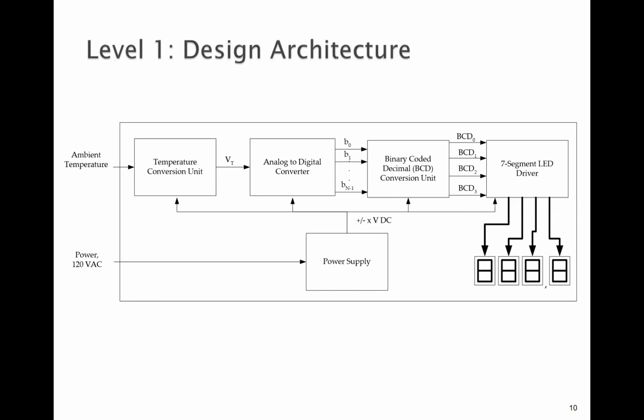We have 2 inputs, ambient temperature and power. So this block here actually shows our digital thermometer in the previous level 0. The first block is the temperature conversion unit. It's an RTD, as it's recommended or defined by the requirement.